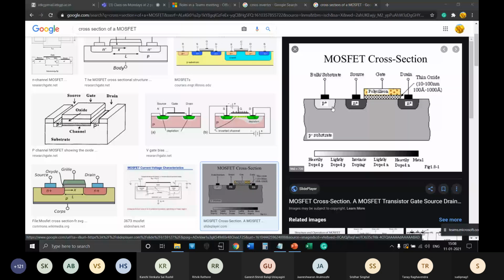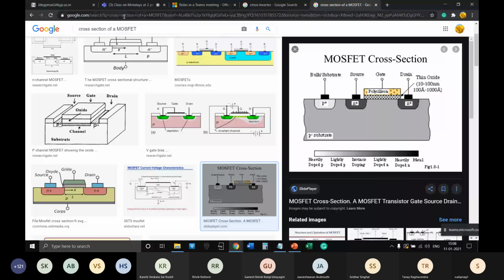And obviously, this is an n-channel MOSFET, so there are source and drain terminals. The distance of the substrate connection is different from the source as compared to the drain, right? And these two are close by. So whichever terminal is closer to the substrate connection, or the doped area for the substrate connection, we call that the source, and that is already defined by the manufacturer and also defined in the schematic symbols in LTspice for NMOS 4.